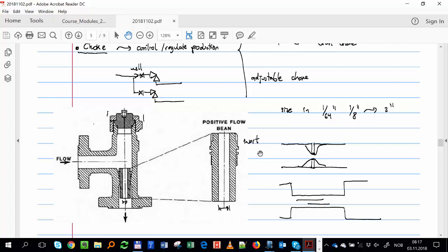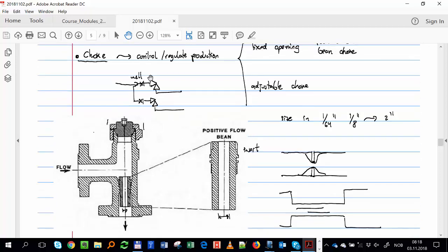and typically from 1/8 to 2 inch. But if I want to regulate my flow, let's say reservoir pressure goes down, and then I want to keep the same rate, I have to stop the well, open here, change the insert, and then put the well back in production. Or I might have a choke battery where I'm working on one, and then while the other is being changed.